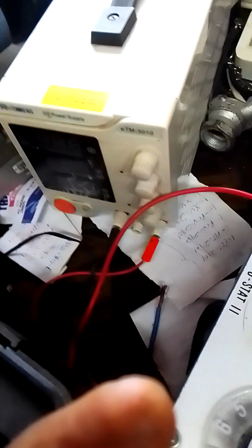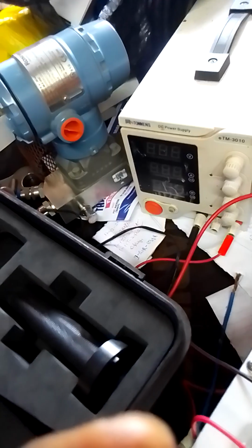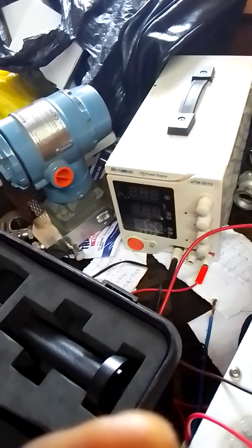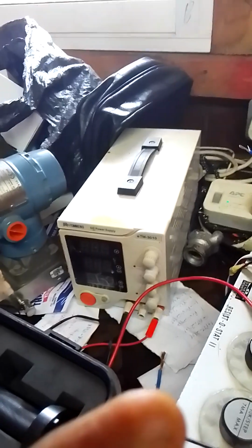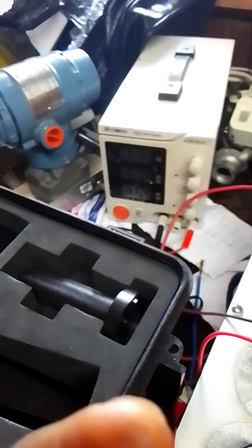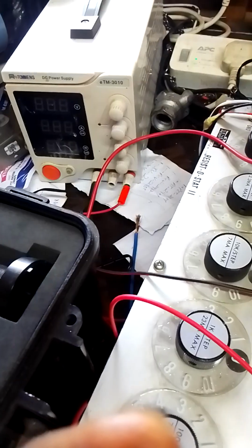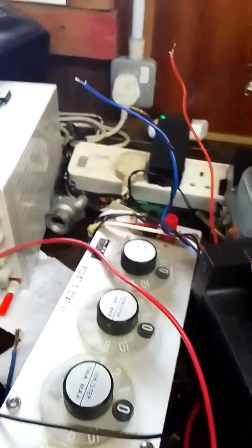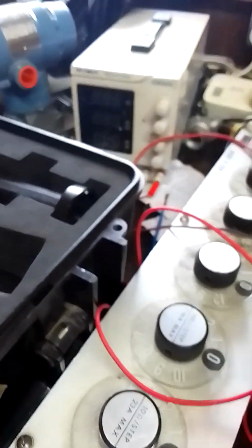The black is the common, so the common carries two wires, which are the black and the blue, while the positive part of it carries the red. You can see it. At times you have 3 wires. These two represent compensation and common, while this one is the main exciter of the thermocouple, or the temperature element. So when you increase your resistance value, as these are connected to your transmitter, the temperature increases. But for this video, it's just a surface explanation. That is that for this.